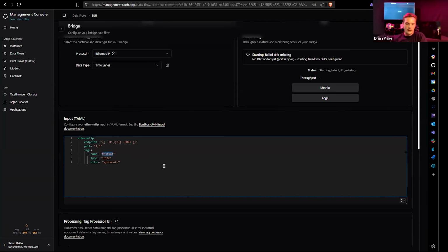All right, so now we know what that tag is. So we're going to go ahead and put that in here. So viz tube fault pilot light. That's what the PL stands for. And we know that it's a bool, and there is no alias for this. So this just gets us started on the input side of things.